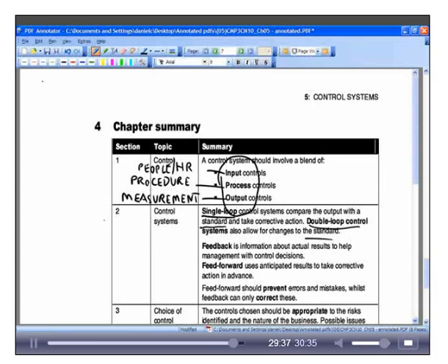Just quickly looked at the terms feedback, which is information about what has happened in the past, and feed forward, which uses information for what will happen in the future, both of which can be used to control systems and ensure things are kept on track. Notice one of the differences between these two is that because feedback is fundamentally backward-looking, it can only take corrective action to deal with errors that have already happened. Feed forward can actually prevent errors because it's forward-looking.